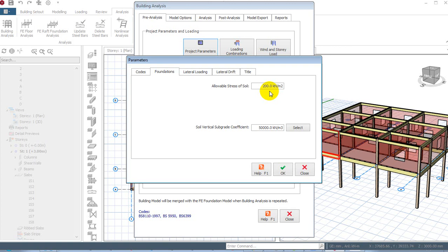So we use more of pad foundation here in Kaduna, but in Lagos, which is very popular, I believe you must have heard of Lagos, the soil bearing capacity in the island part of Lagos is actually very, very poor. It's usually less than 100. So around those areas, they usually use more of raft foundation and pile because it's a waterlogged area.